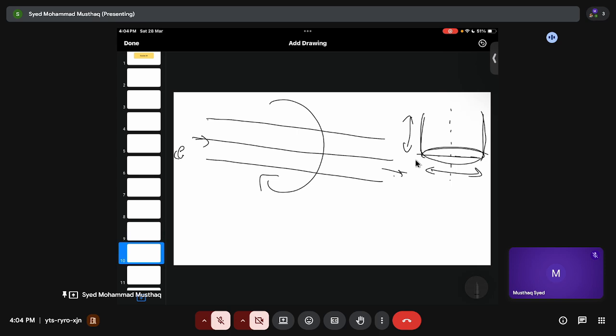Again, in the direct smelting process, the type of ore is also very important. That means the shape of the ore, whether it is a pellet, a lump ore, or a fine ore. Fine ore can be used in the fluidized bed. If you have very large particles, then fluidization is very difficult. And if you have very fine particles, there will be a lot of dust, so that is not suitable. So there is a trade-off between particle size, not very small, not very large. So let's say we use fine ore, we can use it for a fluidized bed.